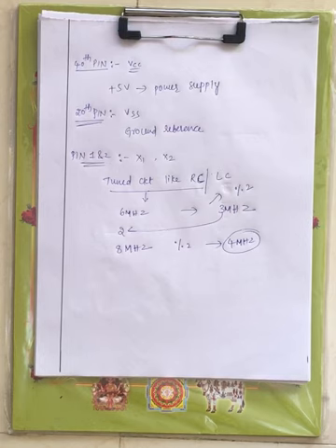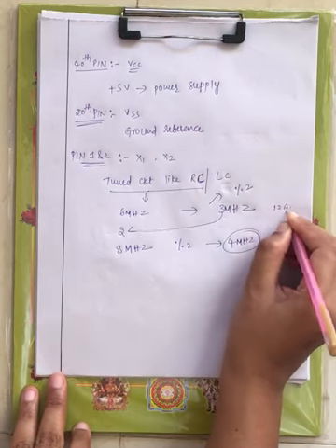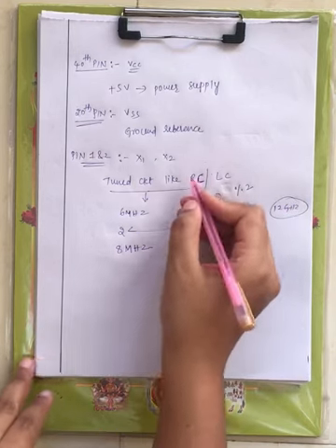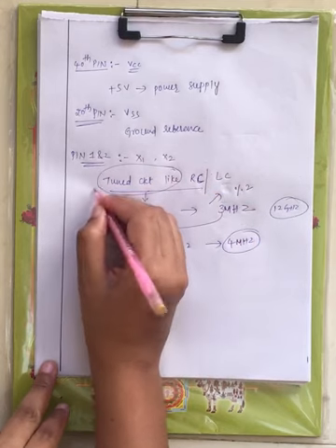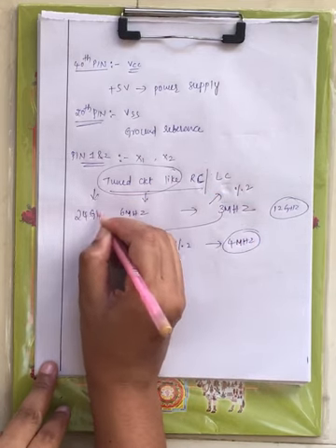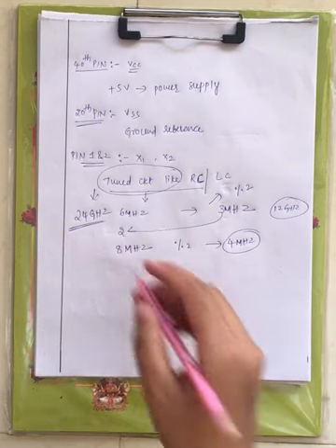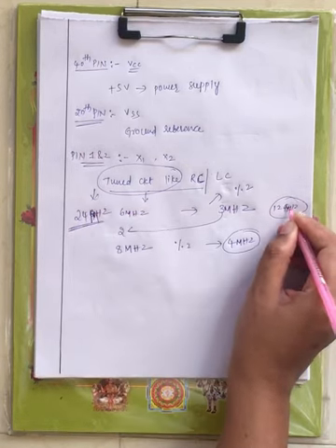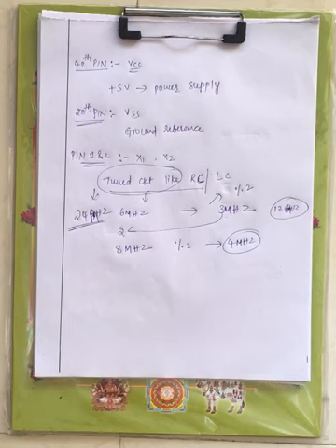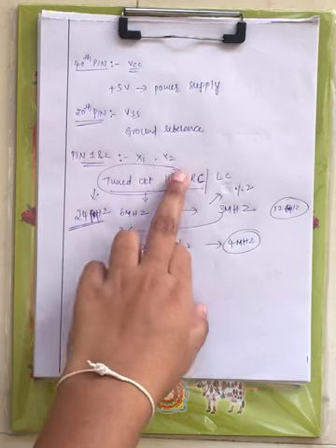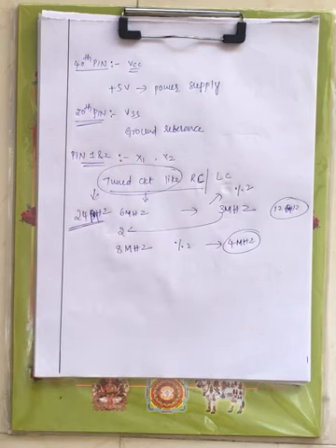Now if you want to operate your processor at 12 megahertz, that means we have to generate an oscillator frequency of 24 megahertz. Basically the processor will operate in megahertz only. But what is pin number 1? X1. Pin number 2, X2. We are providing the oscillator.